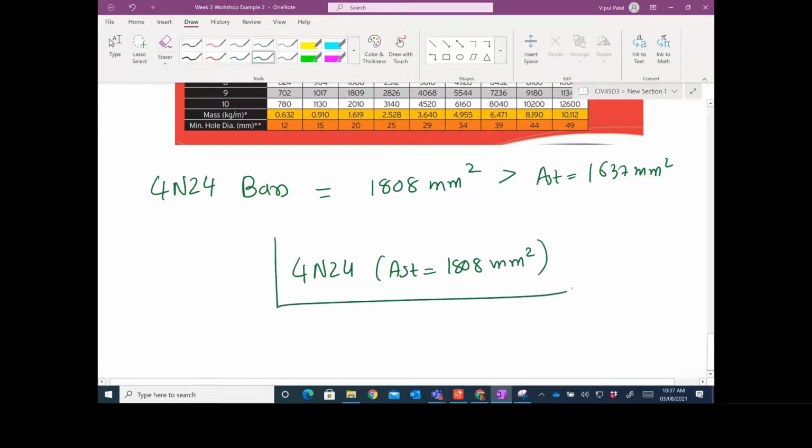That is the longitudinal reinforcement required to carry this M star value of 300 kilonewton meters, right? Because the concrete alone will not going to carry all the loads. So we need to find those values. Now we need to do the couple of checks as well, ductility, minimum flexure requirement checks, and so on. So let me do all the checks that I skipped in our first example. So let's experience this one slowly.